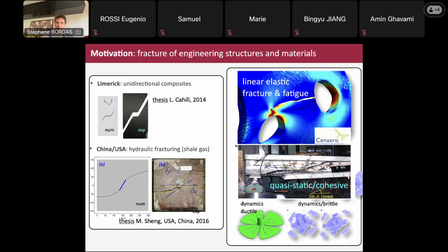So anything that's at the bottom of a beam under bending, you will have tension. At the top, you'll have compression. Therefore, at the bottom, you will need to put some other material, usually steel, in order to help the concrete be able to withstand the tensile part of the load. And that's very important to understand.